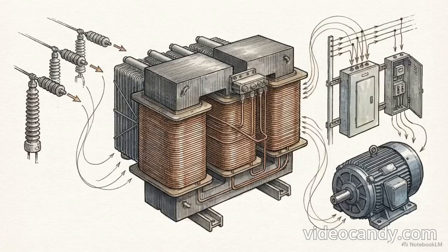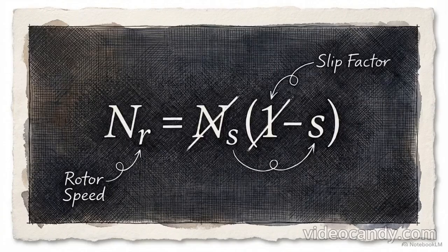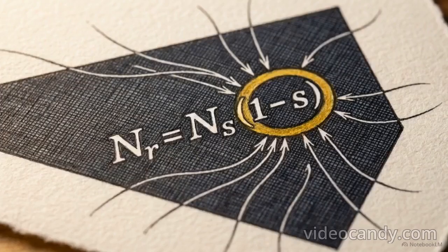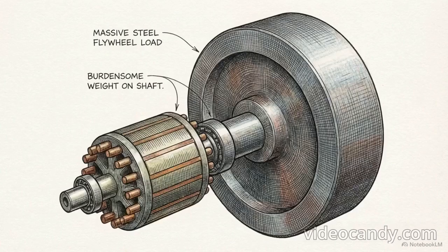Today, engineers often use a hybrid approach, the current-regulated voltage source inverter. This uses standard compact VSI hardware, but implements advanced software control loops to force the drive to output the dynamic, precise current profiles of a CSI. To get precise control out of a rigid AC motor, we have to isolate it from the power grid entirely. We tear the raw, rigid utility power down to direct current and completely rebuild it from scratch to fit the load. There is a completely different approach to AC control.